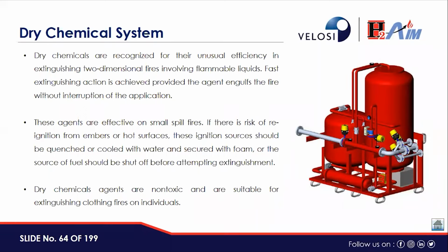If there is a risk of reignition from embers or hot surfaces, these ignition sources should be quenched or cooled with water and secured with foam, or the source of fuel should be shut off before attempting extinguishment. Dry chemical agents are non-toxic and are suitable for extinguishing clothing fires on individuals as well.